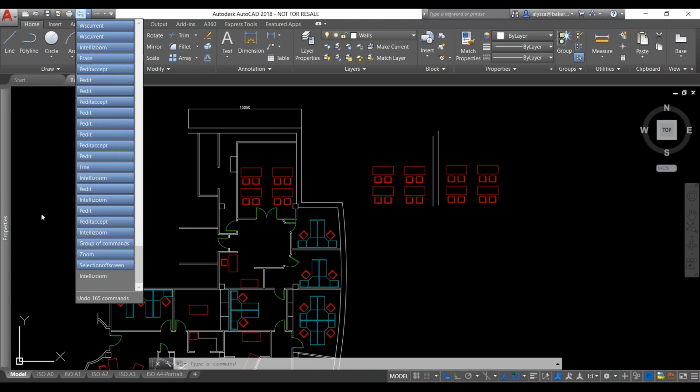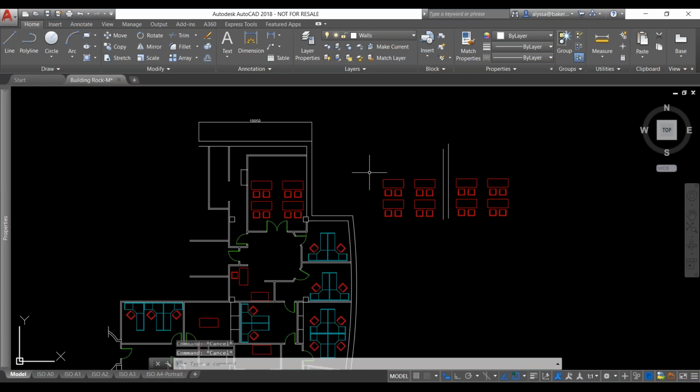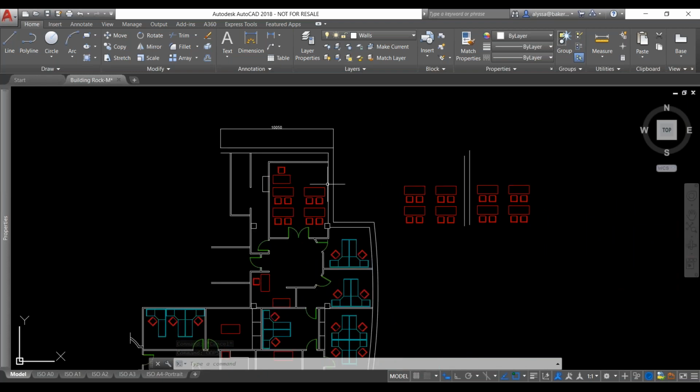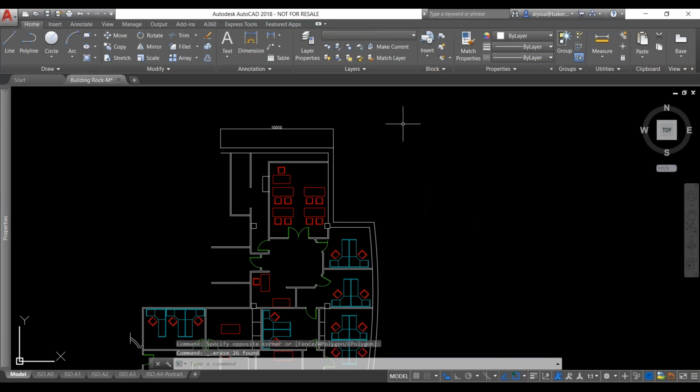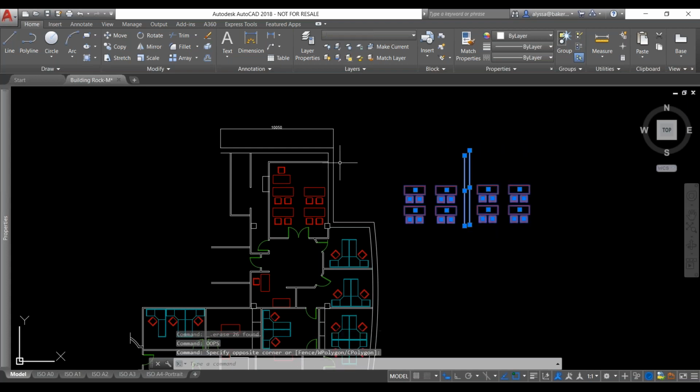If we're so far that we don't actually see one of our lists here, specifically the erase last object, what I want you to type in to retrieve that last erased object, irrespective of how far down the line you are, is oops. Press enter, and it's going to bring back that last deleted item, instead of undoing a whole bunch of information. So that's a little bit of a helpful hint. That's typing in oops to just get the last erased object back.